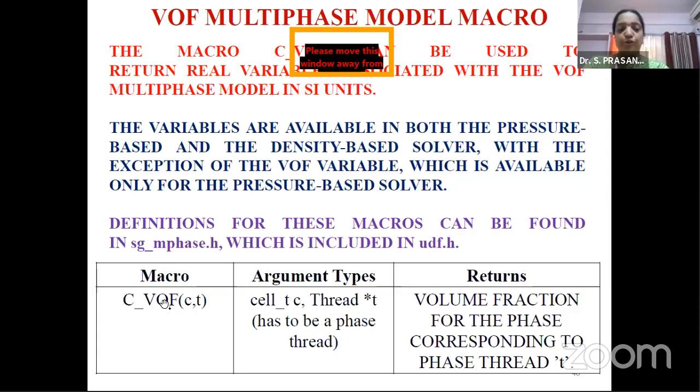You have to run that code using these macros. There are so many macros available, for different types of pressure, for dynamic pressure, x velocity, y velocity, for each and every parameter that you can visualize by means of contours and vectors. For each one, you have a macro which is run to know the numerical values of the flow taking place in the control volume.